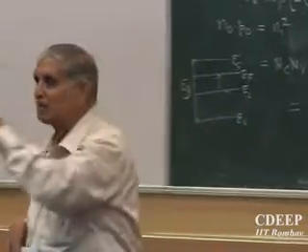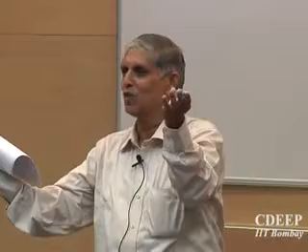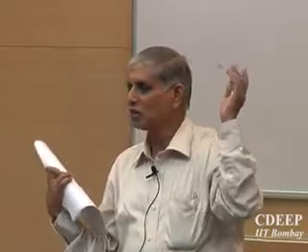Actually, what is my ultimate aim to derive? The current versus voltage, capacitance versus voltage. For electrical people, we are only interested in these two. If we can get these relations for the circuit, I know the equivalent of that device. I would correspondingly see I have a current source or a capacitive variable, and I solve the normal circuit using network theory, either using the Kirchhoff current law or the voltage law. I can always solve any circuit.